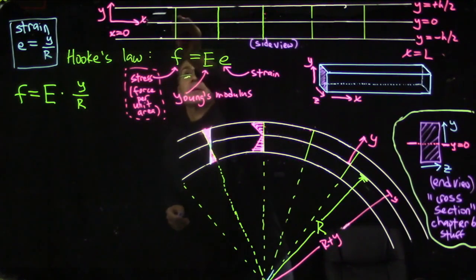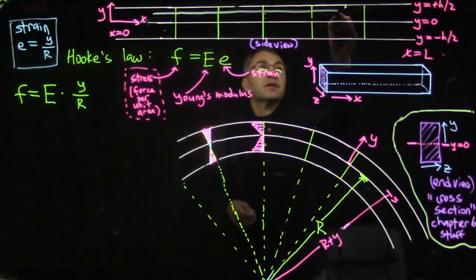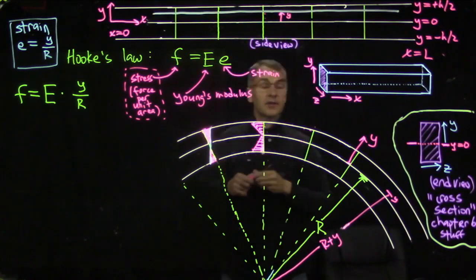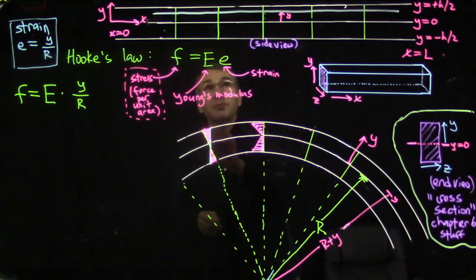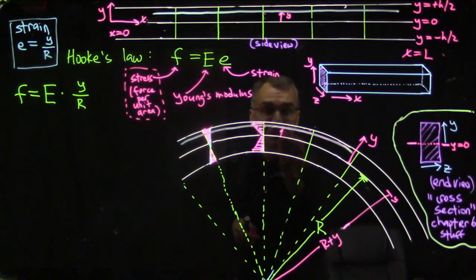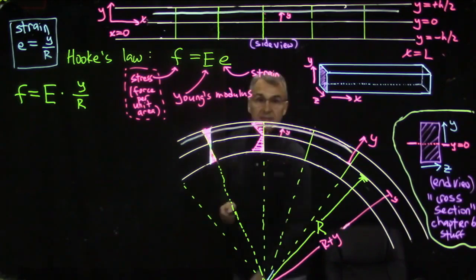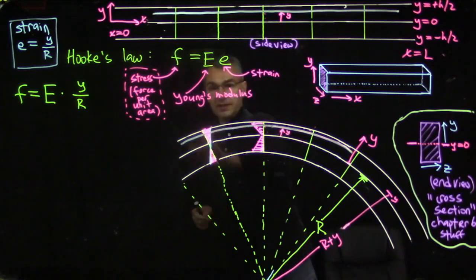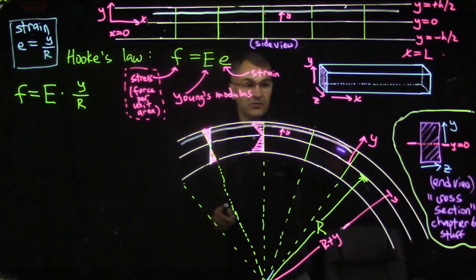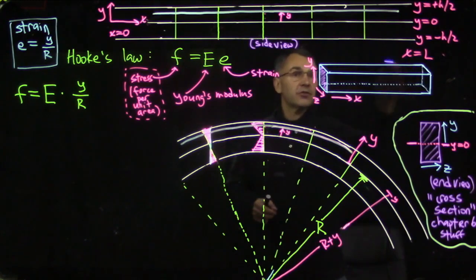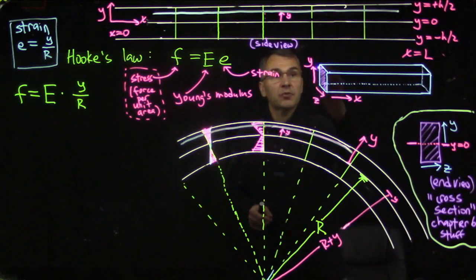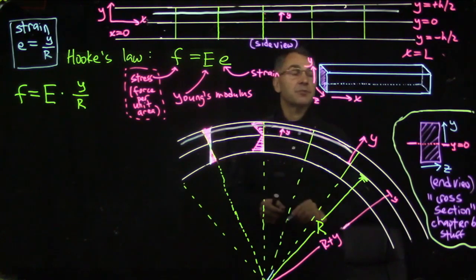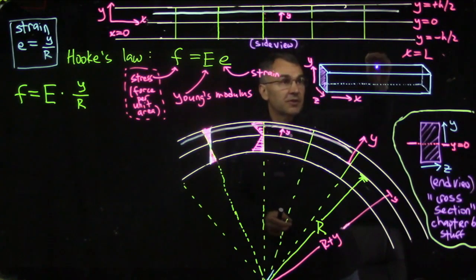Now let's pick a fiber going along the length of our beam. So we're going to pick a fiber up here at some height y above the neutral surface, and so on this bent beam that fiber will be up here, and here is the height y above the neutral surface. And then we can look in this other projection. So we've been looking at the y versus x, and then here is the bent into a circular arc x, and we have these radial y values. If you look at this kind of three-dimensional image of the beam, here's x running along the length of the beam, and here's y going upward perpendicular to the axis of the beam and opposite the way gravity points in the unbent beam. Usually the load that we apply on the beam is in the negative y direction.